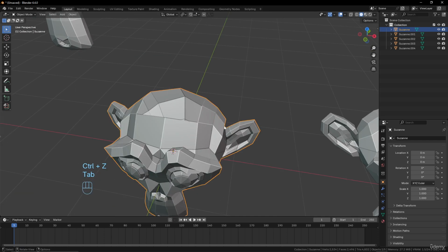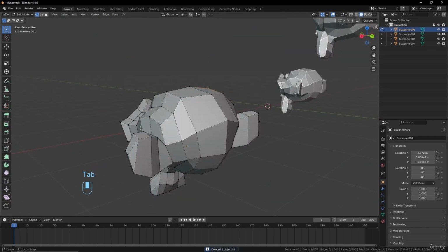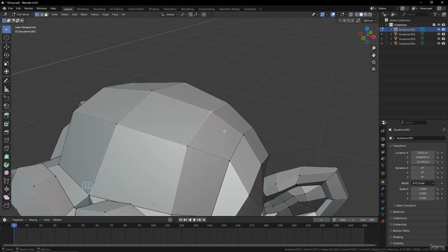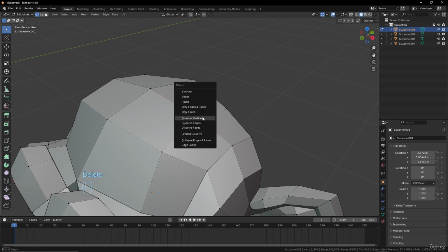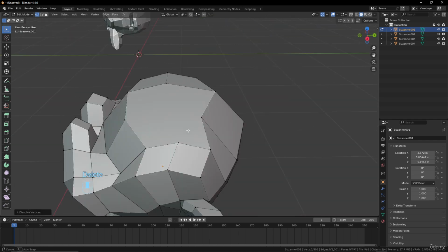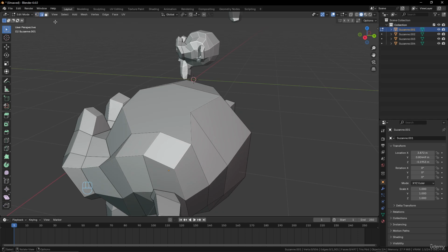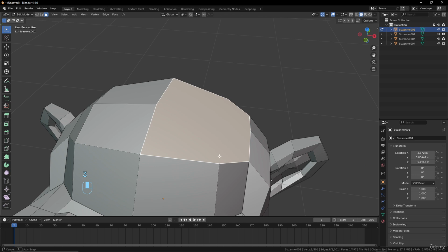You can choose to remove some geometry and keep the surface behind. Like for example, if I want to remove this and keep the surface around, I just use the same way, but I will use the dissolve here and I will dissolve the geometry like that. But I still have a big face, strange one, but still have a big face here, okay?